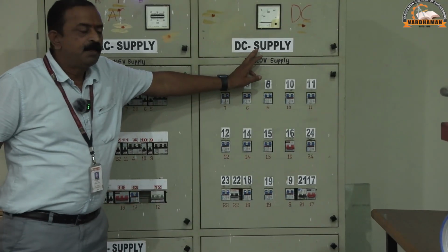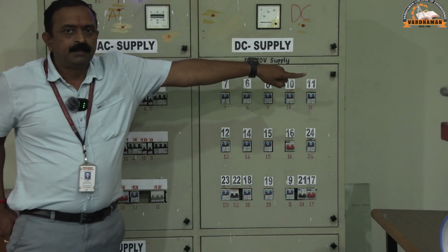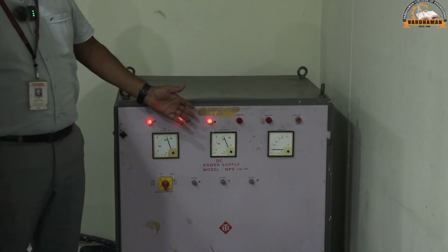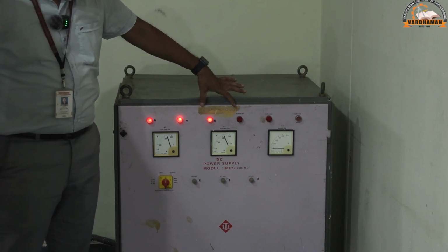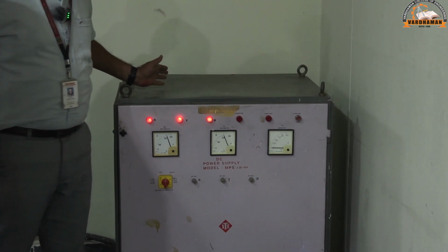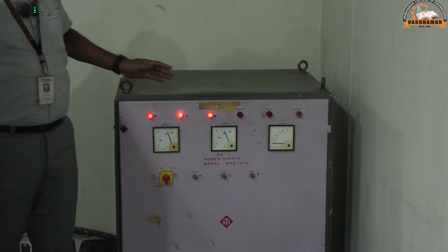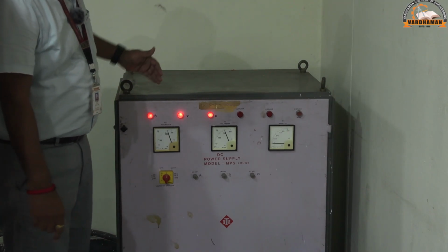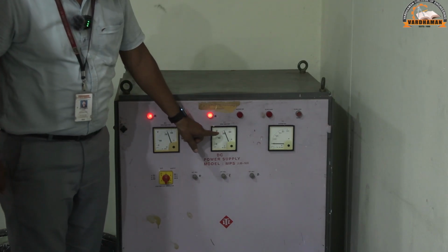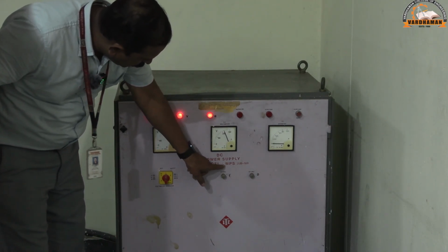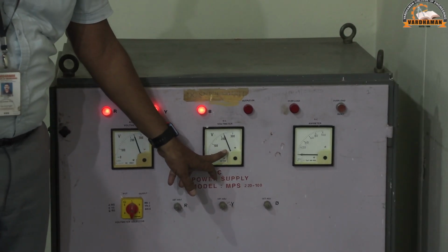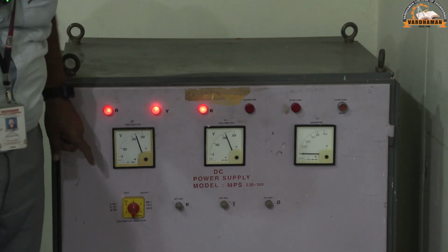When coming to the DC section, we have an equipment at the backside of this panel that is called a rectifier. So this is the DC rectifier. The input to this equipment is three-phase AC. It further converts it by the use of SCRs, silicon controlled rectifiers. So this is going to convert that three-phase AC voltage into DC voltage. The ampere rating of this kit is 100 amperes, and the output voltage we will get is 220 volts. That we can see from the voltmeter erected.